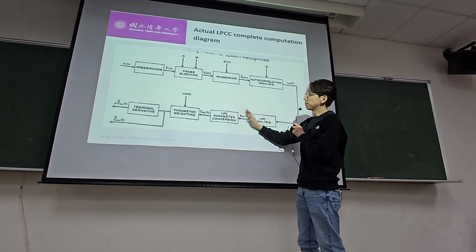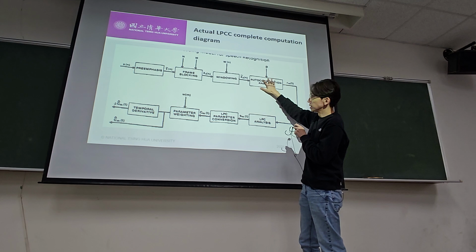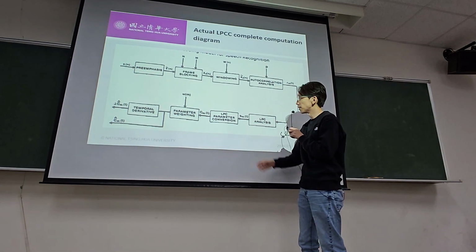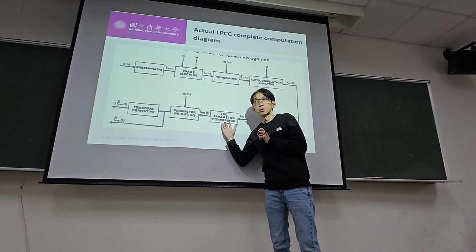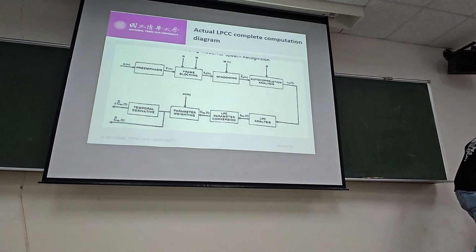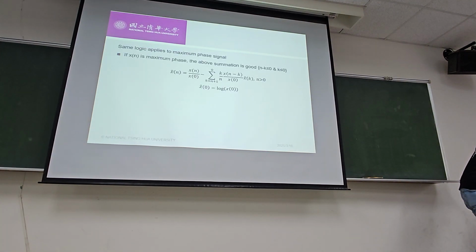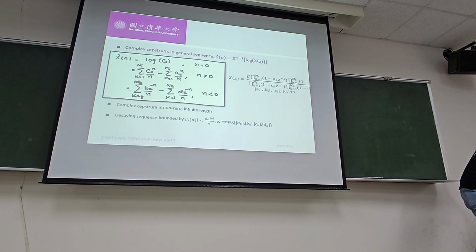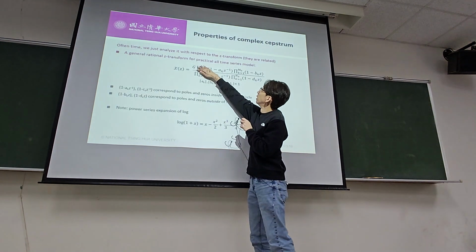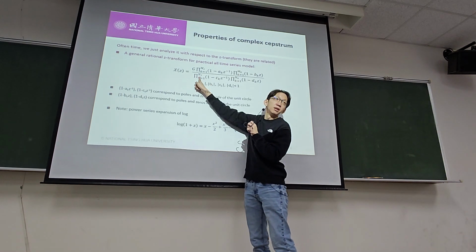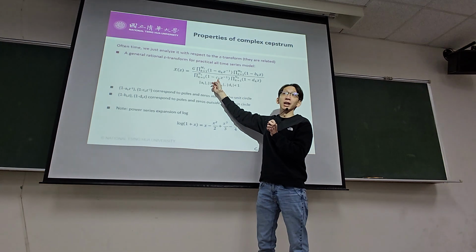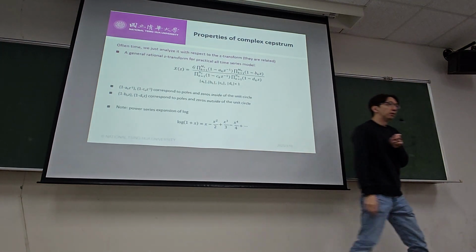Taking the LPC coefficients, you do this kind of LPC analysis, which we already know from a few chapters back. Those filter coefficients are the poles, the alphas. If you remember back here, the LPC model is just this part, an all-pole model. So the alphas you derive are all the a_k's.